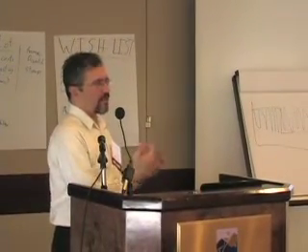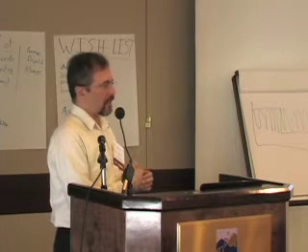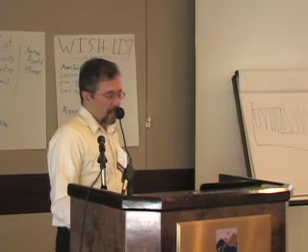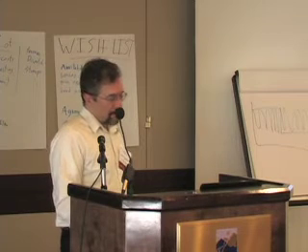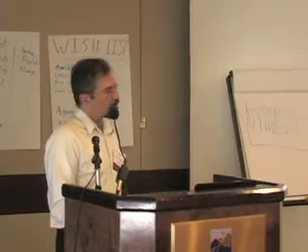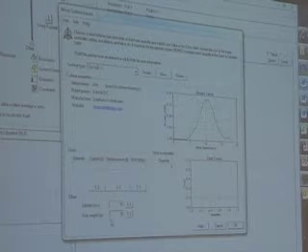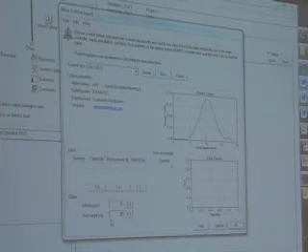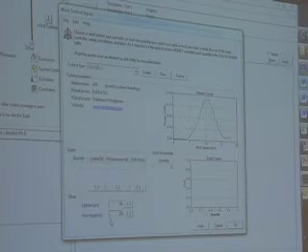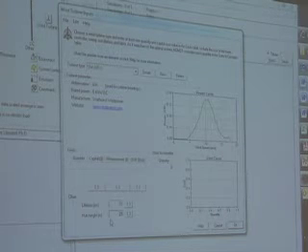I couldn't tell you off the top of my head exactly what the formula is, but you figure out the air density. The other adjustment we do, so here's the hub height. The shear factor uses those two parameters, the anemometer height and the hub height together, to adjust for the increasing wind as you go to higher heights.